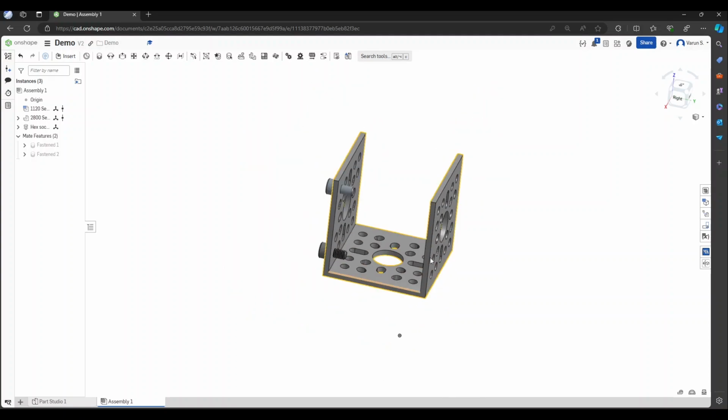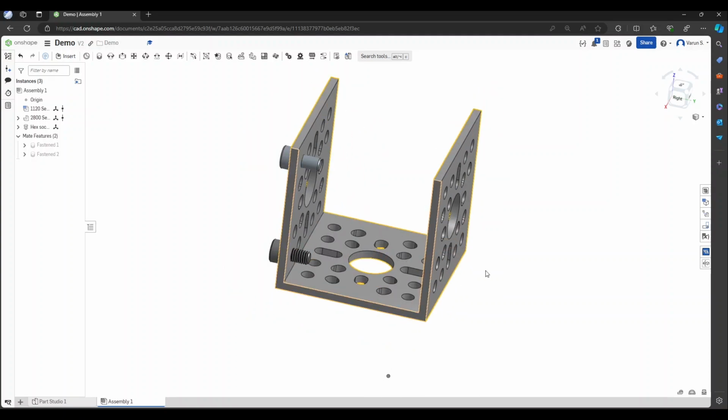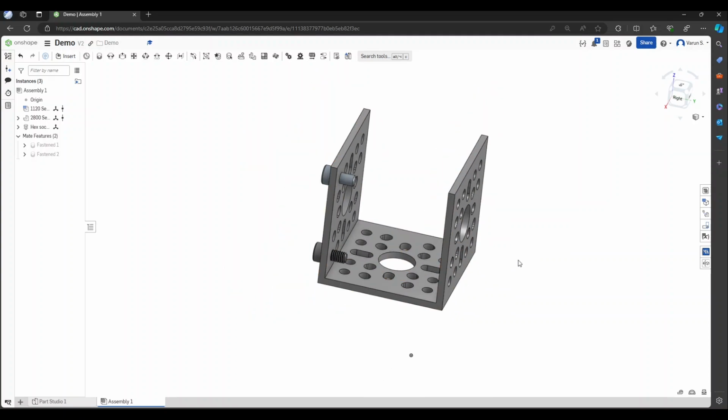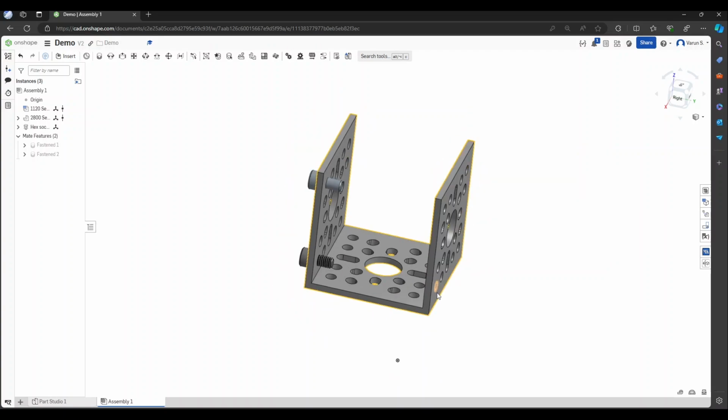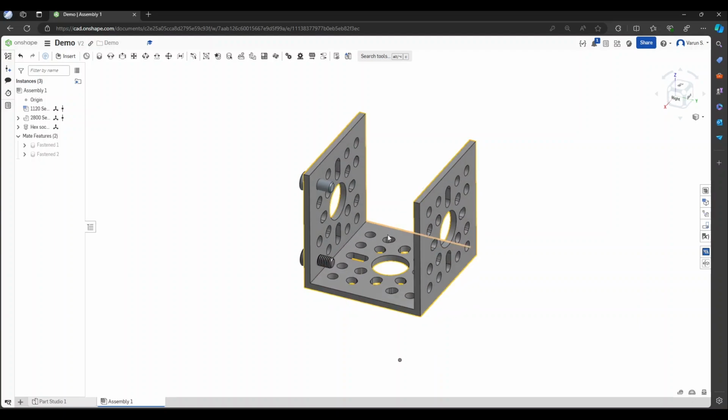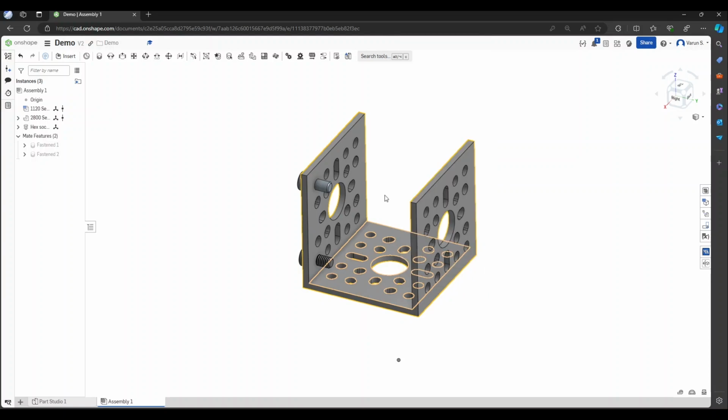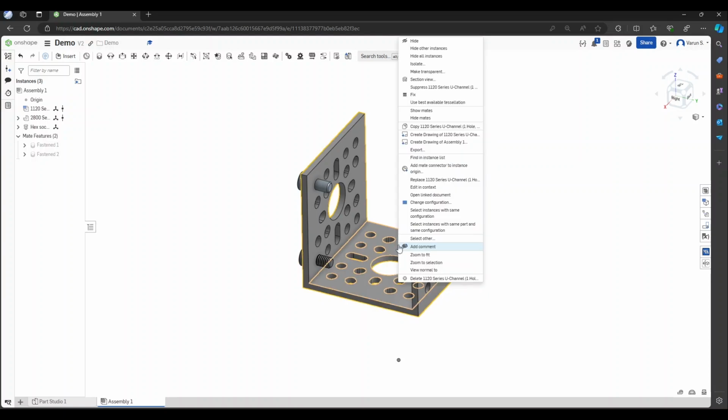And trust me, when you get into larger assemblies and for some reason it is not actually fully constrained, it becomes really annoying when you're trying to add parts and suddenly your entire robot is upside down. It's weird. So anyway, you want to fix the U channel. And so the way you do that is you can just right click on it and it'll give you the option fix.